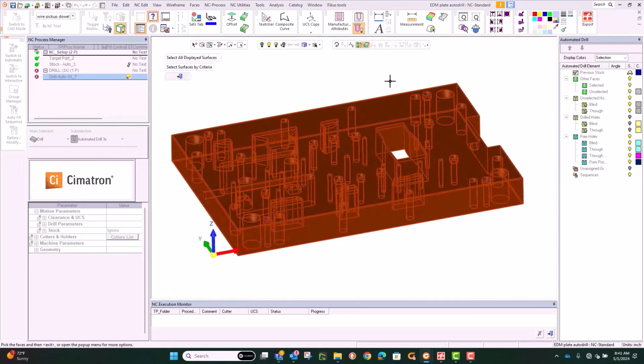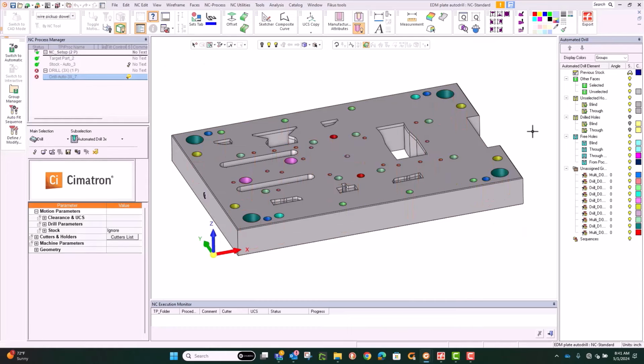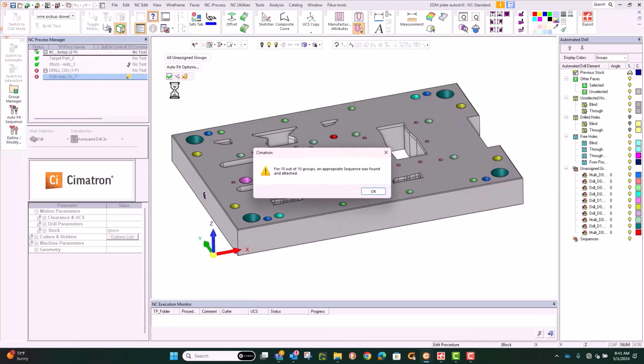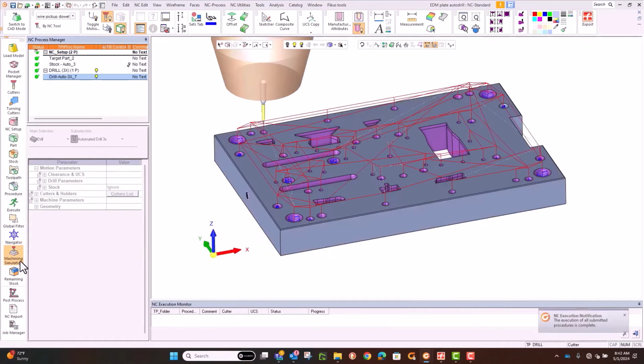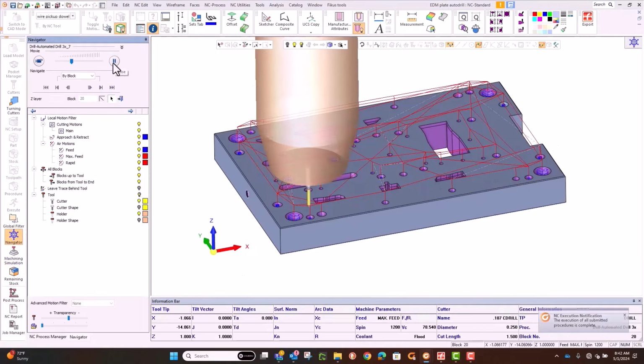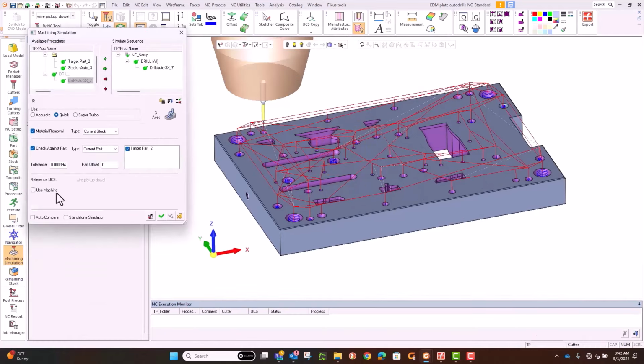Now we're going to target the holes. There's a lot in this when you think about what's involved with holes. Set this up as a 3-axis drill program, tell the system, go find the holes. There they are. Now group them. So it groups them according to the size, diameter, configuration. Is it counterbore? Is it through hole? And then we'll run it through our list of sequences, different operations, like a library of drill hole strategies.